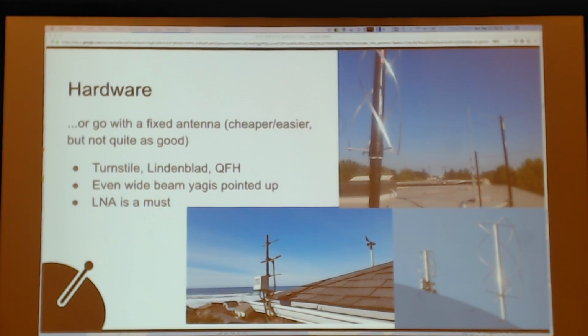The interesting thing about this project, when it was first started, the assumption was that we would need high-gain antennas and therefore directional antennas with rotation to be successful with collecting data packets from CubeSats in low Earth orbit. What we found is that people started popping up on the network with omnidirectional antennas, and they worked. So now there are a lot of documents on the wiki on how to do this, what works, what doesn't.